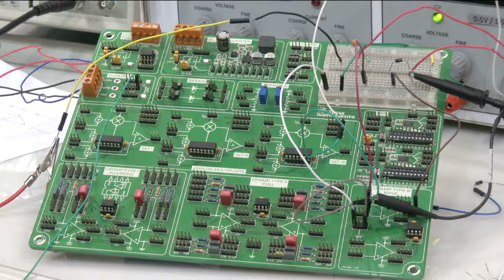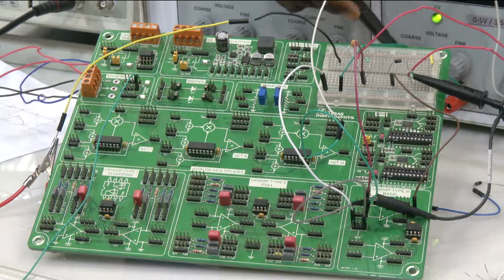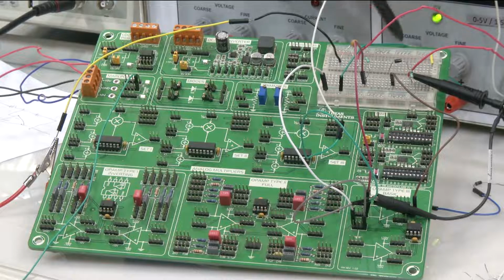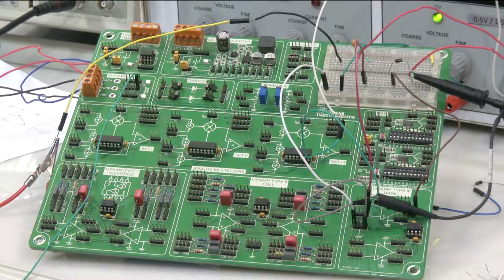If you recall, we connected to the positive terminal using a voltage source. Here, at this point, to the non-inverting terminal we have connected the input, whereas in this case, rather than using a potentiometer, we use this particular 0 to 5 volts channel to connect an input to the non-inverting terminal of the operational amplifier. As a result, the negative terminal of the second channel is connected to the non-inverting terminal, whereas the positive terminal of this channel is connected to the ground.